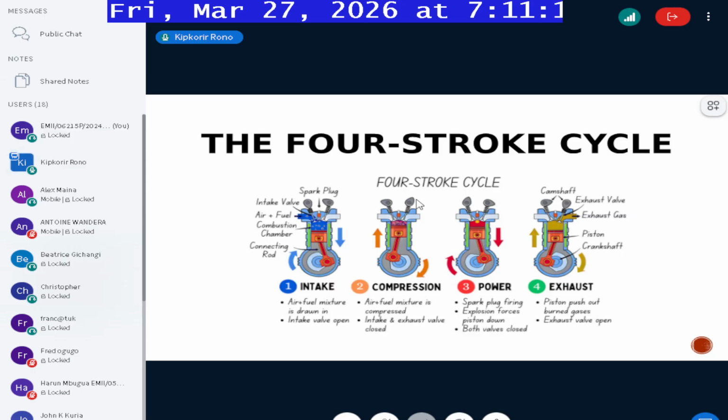The internal combustion engine has a problem that is commonly observed. It's what contributes to its thermal inefficiency. There's something called thermal efficiency. Once the exhaust valve has closed and not all the exhaust gases have left, then in the next cycle, during compression and power, we'll be combusting air and fuel plus some products of combustion, which cannot be combusted any further.